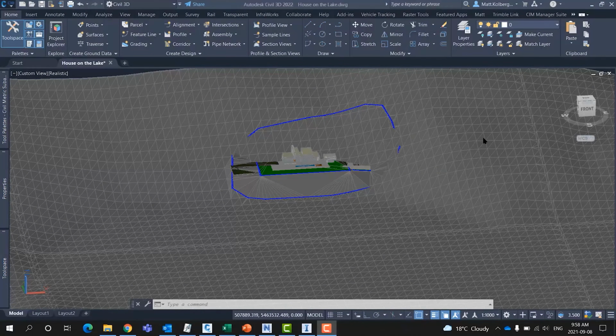And here's the Revit building inserted into the AutoCAD drawing on top of the InfraWorks terrain. I've already done some basic grading, and the grading that you'll do in Civil 3D is just your typical grading. Create a feature line for the building pad, do some daylights. I've moved the Revit model horizontally and vertically in order to line up with that building pad. We can now create the shared reference points in Revit so that everything will line up nicely in the future. We'll talk about that later.